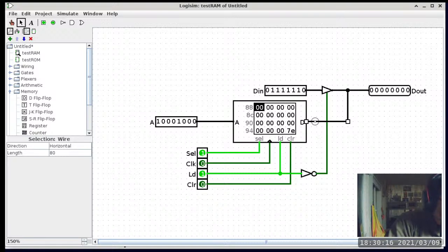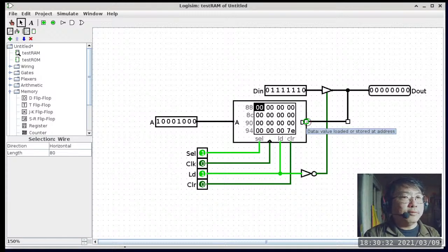Next question is, how does the RAM data port act as both input and output? Internal to the RAM component, it also has its own control buffer inside, and that's why it can change its direction. So it's not usual that we have a port on a device that is, quote-unquote, bidirectional, and the RAM is one of the few components that has a bidirectional port.